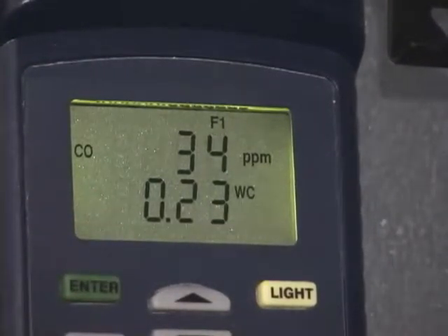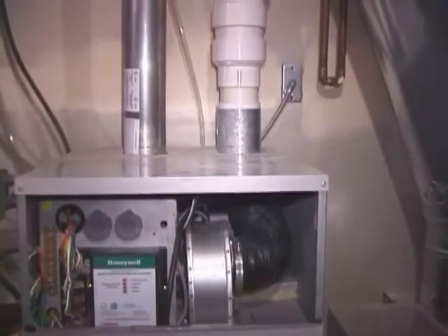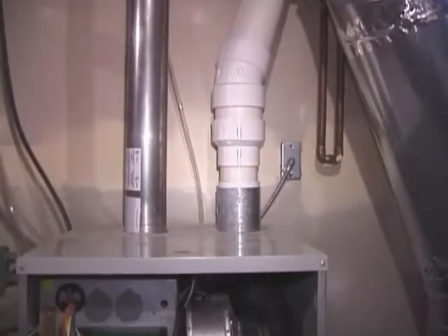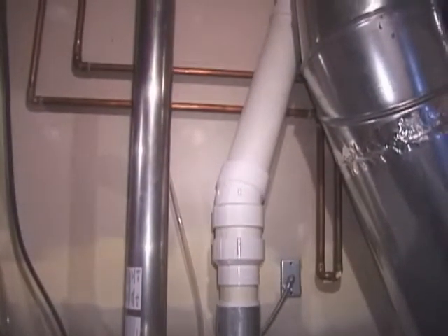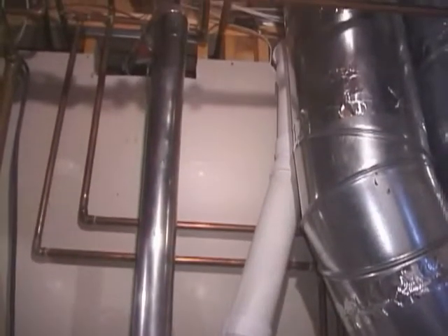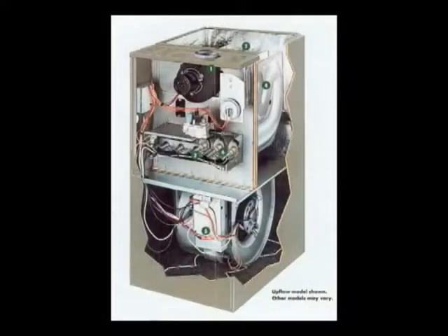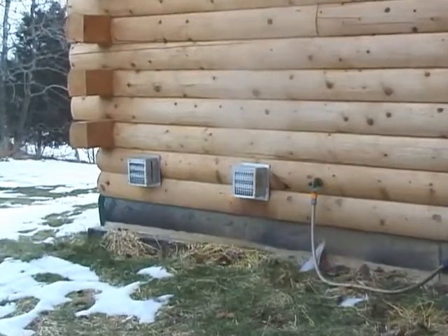A positive vent static pressure simply means that the pressure inside the vent is higher than the pressure in the combustion appliance zone. In Category 3 appliances, the positive pressure in the vent system is created by the fan in the appliance. If there were a crack or hole in the vent at this point, combustion gases in the vent would get pushed out into the combustion appliance zone. An example of a Category 3 appliance would be a mid-efficiency furnace that is vented horizontally through the wall.